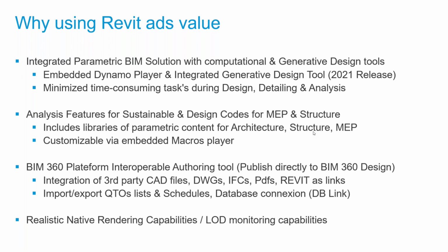Revit also has links, a bit like you do usually with the Xrefs in AutoCAD or AutoCAD Plant. And you have the ability to export a lot of quantities, you can do schedules, and you can also connect to external databases. If it's a SQL Server database or Access, you can connect, and you can basically export an entire Revit project very easily using the DB Link capability.